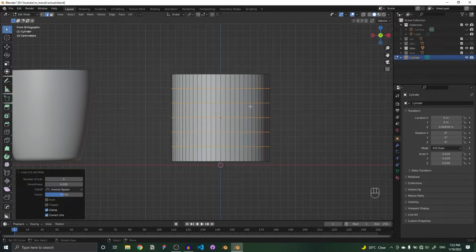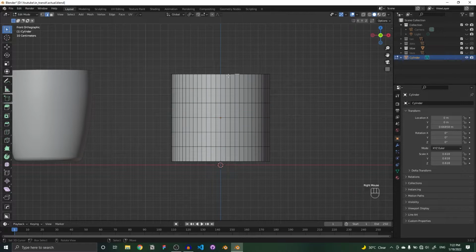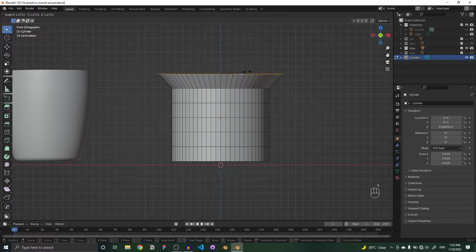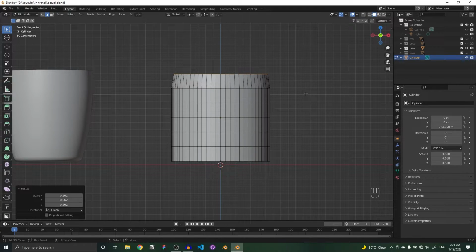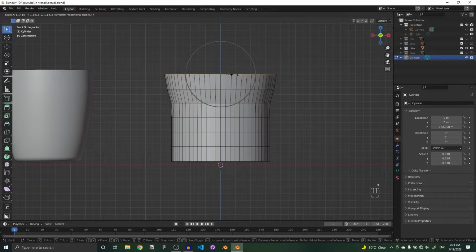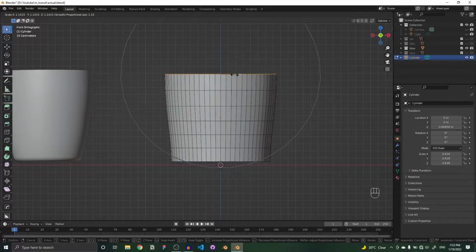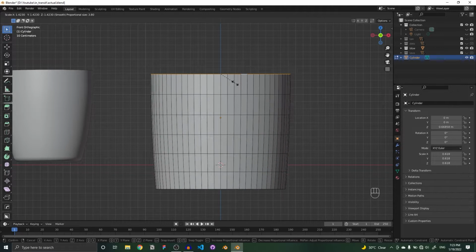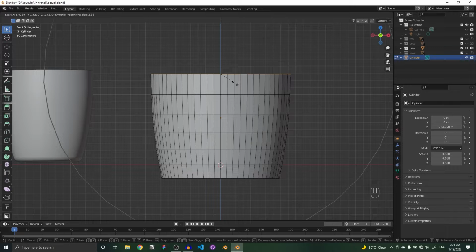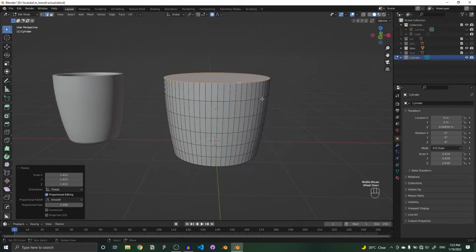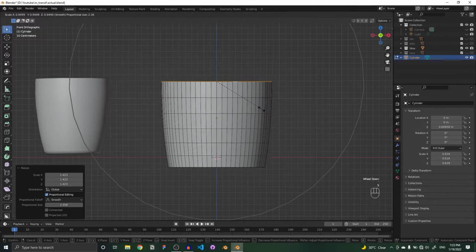All right. Now we're going to do the same thing again. Hold the Alt key once selected and then click on the S key and then you can increase or decrease the size. The key thing which I want to point out here is that, Control Z, if I use the proportional editing tool, it's way easier. So if I click on S again, I can increase the amount by which the sections get affected. So just by using my scroll button, I'm able to do this. See? All right. So front view, I'm just going to decrease the size.